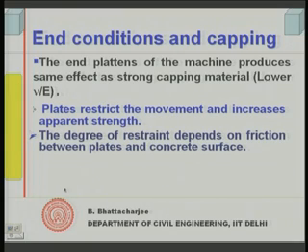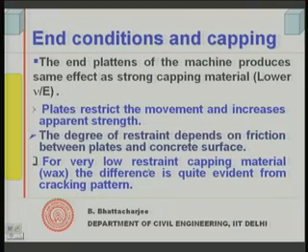This degree of restraint depends upon the friction between the plates and the concrete surface. The higher the friction, the more the restraint will be, and of course the frictional force is itself a function of the load. For a very low restraint capping material, say wax, the difference is quite evident from the cracking pattern. Now, we shall see the cracking pattern which we saw in a photograph one or two lectures earlier. If you remember, we have seen the failure pattern of the cube.